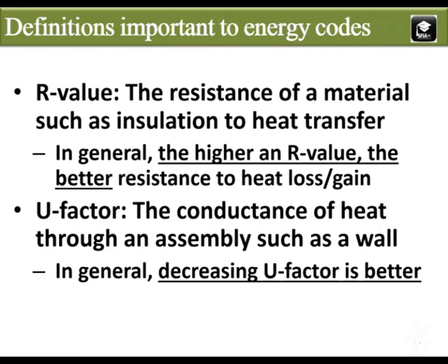The U-factor is another way to describe thermal performance. For example, a wall U-factor describes the total performance of the wall, including the impact of studs, sheathing, insulation, and gypsum board. Conversely, an R-value typically just defines the performance of the insulation or a specific product, such as sheathing. A lower U-factor is better than a higher U-factor, as opposed to the opposite for the R-value.